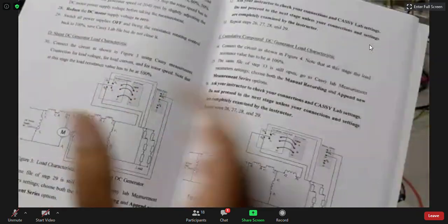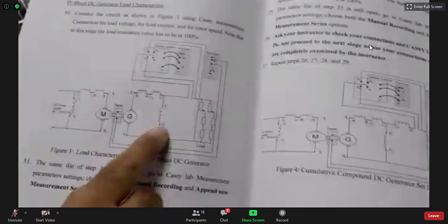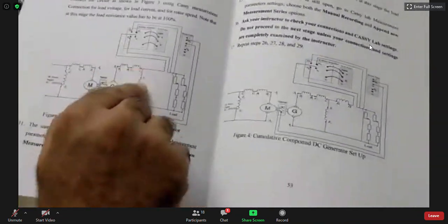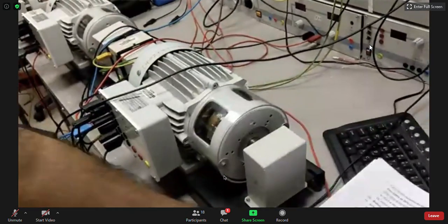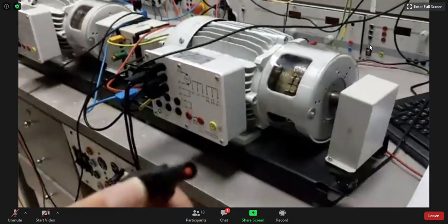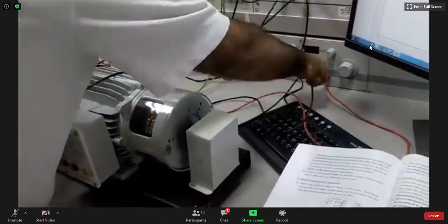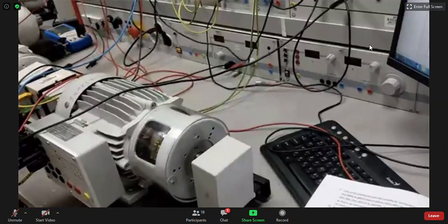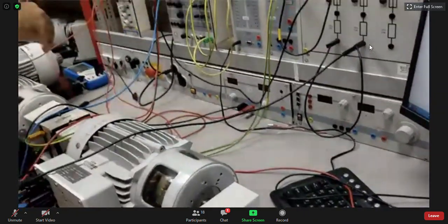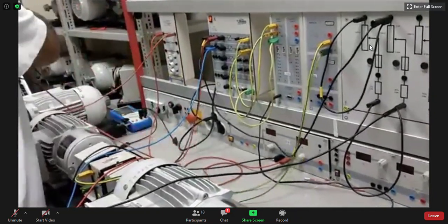So this is what we will do. Basically, we will disconnect the power supply and connect E1 to C1, E2 to A2. Is it clear? E2 will go to A2, E1 will go to C1. But now these two are connected to the power supply. We will just disconnect them. You can see here, this is E1, this is E2. I am disconnecting E1 and E2. They are open circuit, okay? I have to remove the cables from here and there. I'm disconnecting the power supply, and also the fuse is no longer needed. This is the fuse.